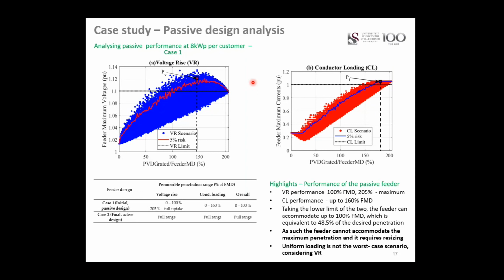For each penetration, you obtain a response, each of the node and branch response for a given number of runs, and then you pick at a given risk level the performance of either the voltage or the conductor as well. I think Mondi's asking if you're running an I²T sort of time series on the transformers and conductors.